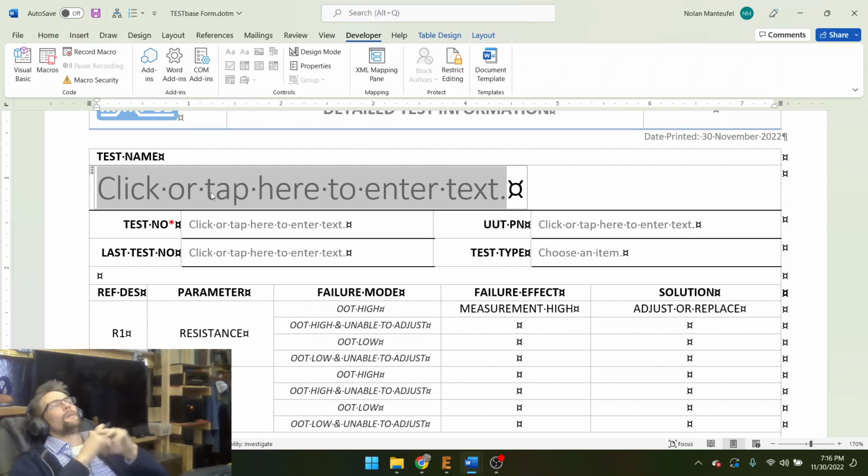Okay, so all your components are going to be playing on that. So you're not going to have a very tight range. It's going to be like, is it less than 100 ohms? Yes or no? Less than 100 ohms? Okay, we may have a problem. More than 100 ohms, like it's 200 ohms or 150 ohms, it's probably something playing with it, but it's probably not short-circuited.